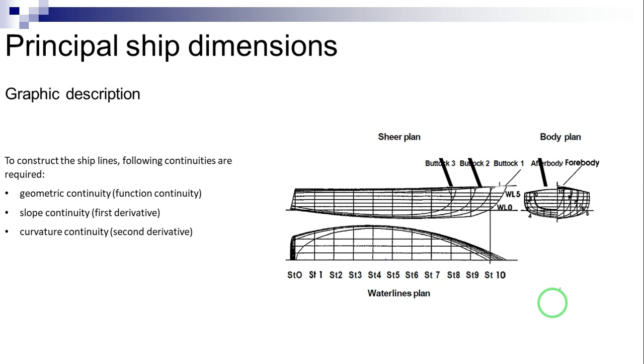Note that the spline in terms of X, Y coordinates is expressed by the differential equation of the deflection of a simple beam, which may become unrealistic when the slope y prime of the line being represented becomes so large that it cannot be assumed equal to 0.